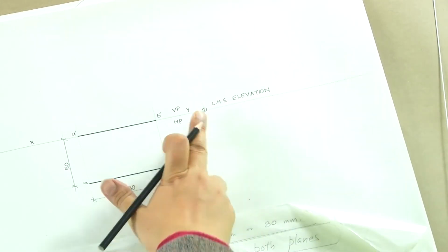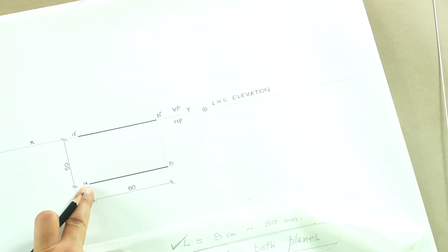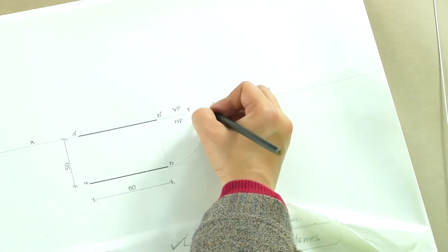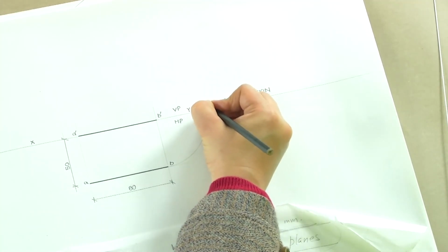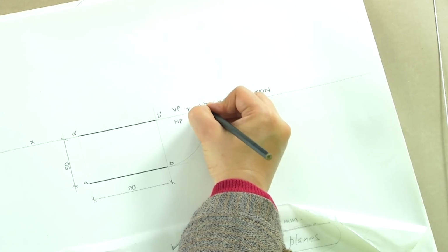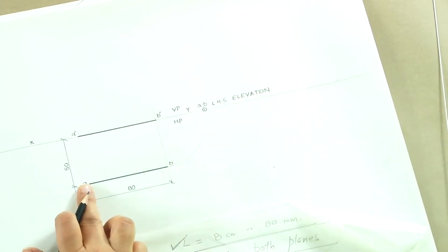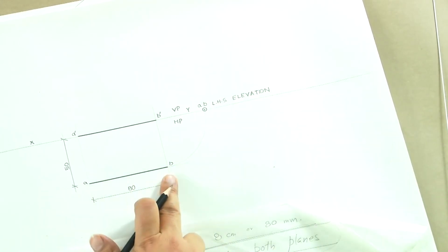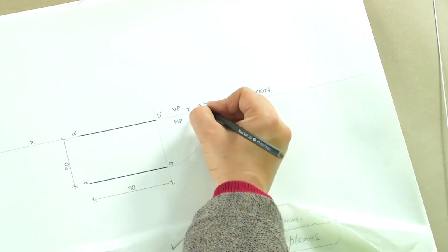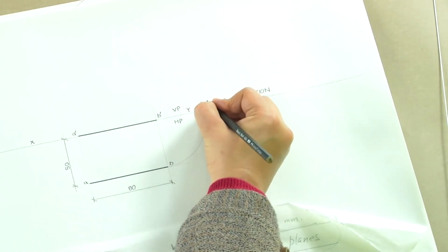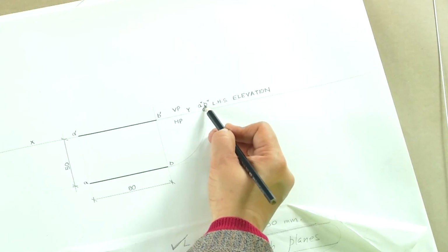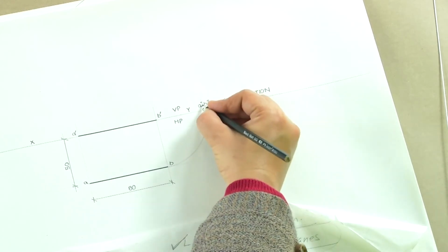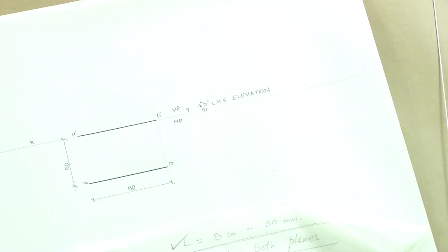And what is this point? This point is actually AB. So we are actually seeing this A, B. Now if we write AB, AB is the nomenclature that we use for the plan. So we will either write A double dash, B double dash, which means that A is in the front and B is at the back. You could also put a bracket here, either of the two.